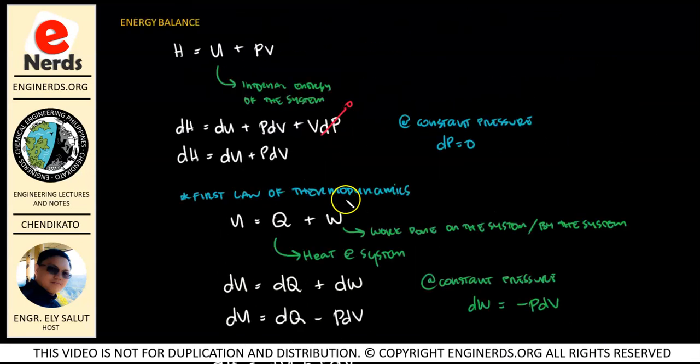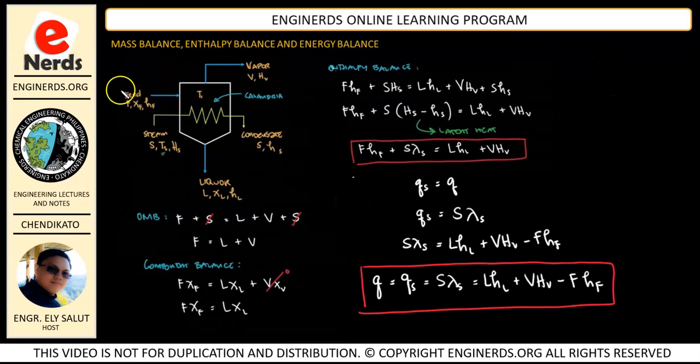Now, let us have a look again at our diagram. We have here a dilute feed. We will be separating some vapor and we will have our thick liquor here. But if the liquor is still dilute, so it is not very concentrated, then the Cp in our system, in the liquor, the main contribution will be the Cp of our solvent.